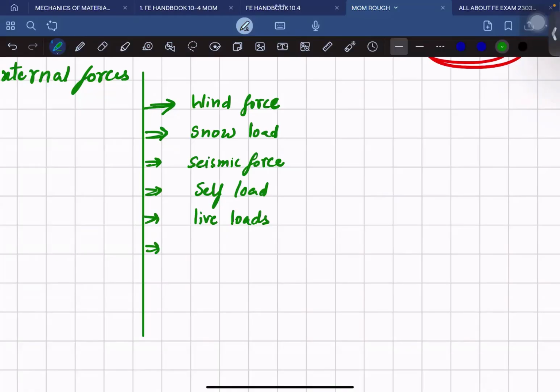Suppose you are in an apartment, in your flat, standing on your floor. You are a live person, you are alive, and the load coming from your weight is a live load on the slab. Isn't that already calculated with a factor of 1.5? Yes, we'll calculate with 1.5 as a factor of safety. We'll just overestimate the loads so that our design will be safer. That 1.5 has nothing to do with dead and live; it's like overestimating your external loads.